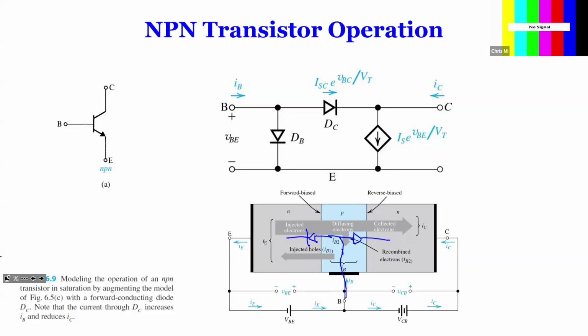It's not a very good orientation, in the sense that the base is over there but this base is over here, so it's not that obvious. If you look at the base, you get two diodes, not transistors, back to back, with the base in the middle. Here on the top, you can see our base coming in, and we have two diodes. The base is in the middle of these two positive terminals of the diode.